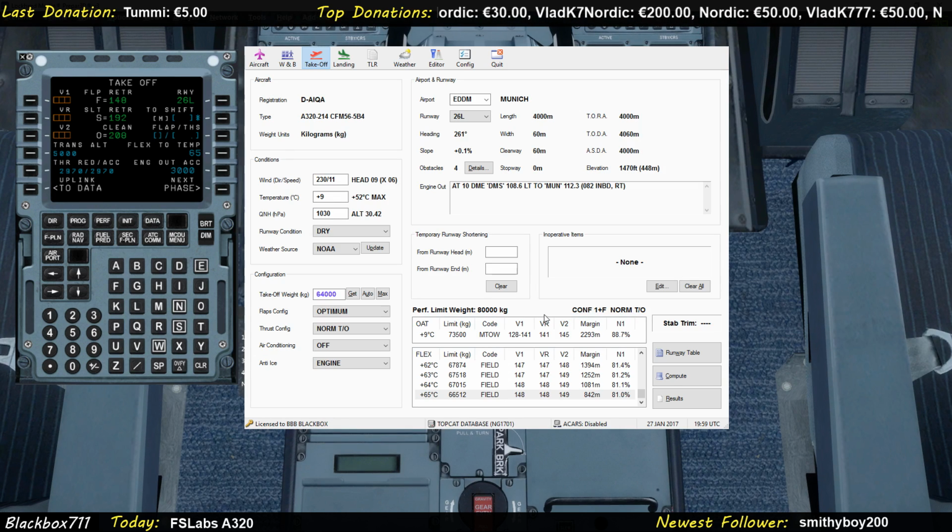When would you use the engine anti-ice? Okay, important thing to do is have a look at the weather. So 9 degrees on the ground is, well, pretty warm. So during takeoff, we have no precipitation. We won't need anti-ice. Now, you could argue if you have an engine failure, you would have to make sure you reach the acceleration altitude. And if you need anti-ice until then, you would have to put that into calculations.